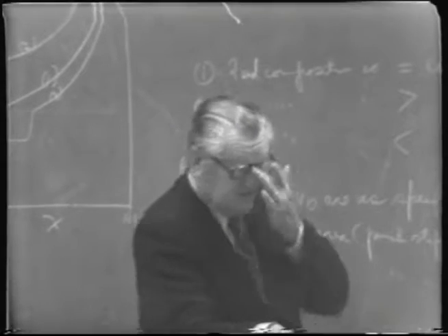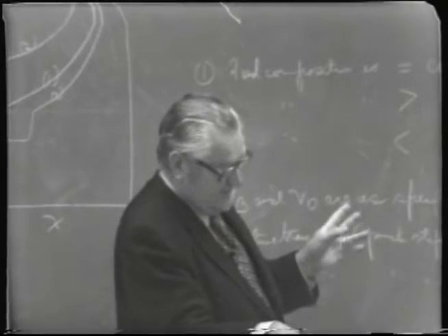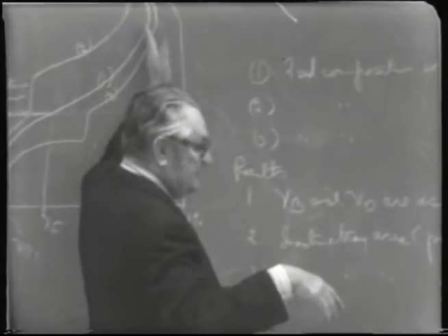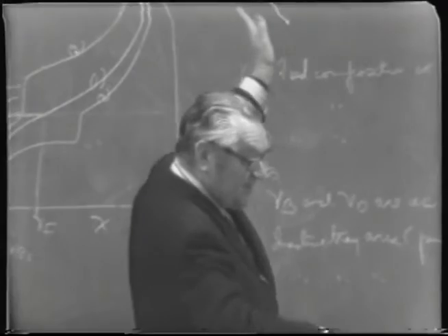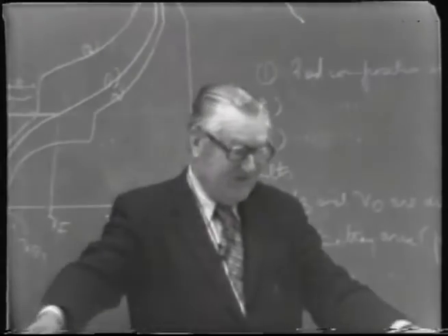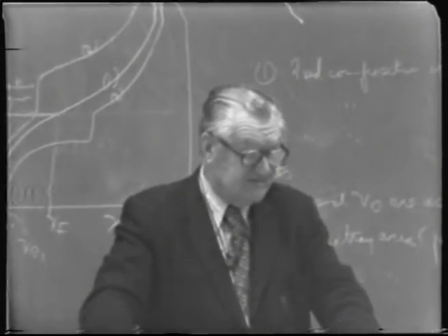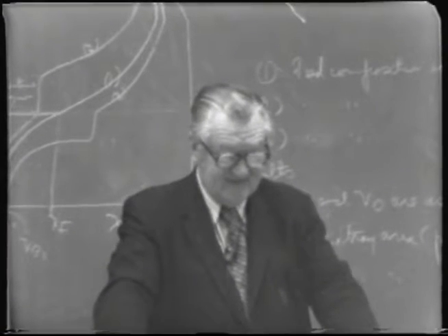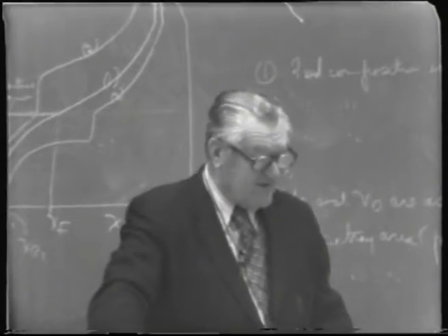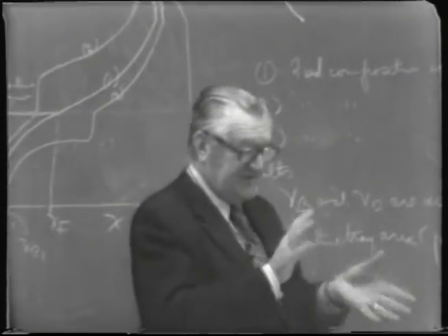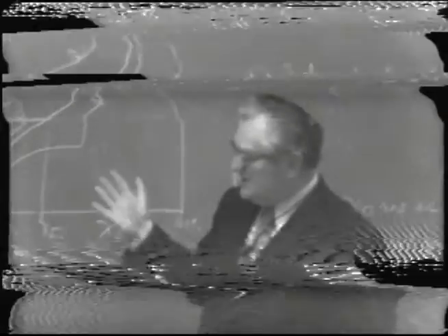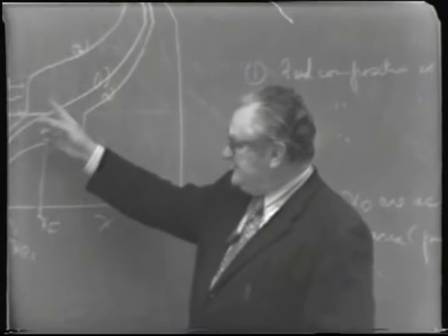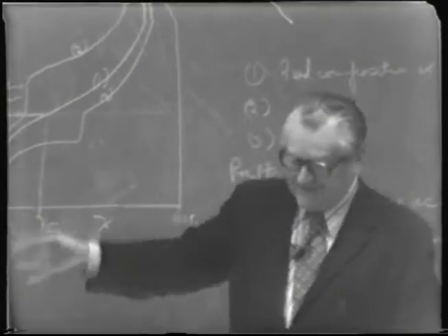I've seen many operators, even producing high proof spirit, getting only 188 or 189 proof at the top, the draw-off point near the top, with 35 to 40 trays, when they could easily have attained 192 proof by changing the operating conditions so that the feed tray liquid was nearer to the concentration of the feed.